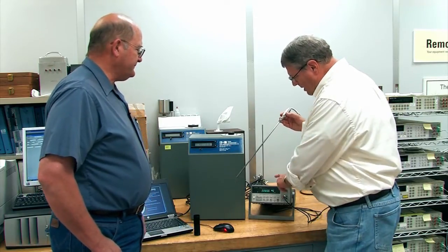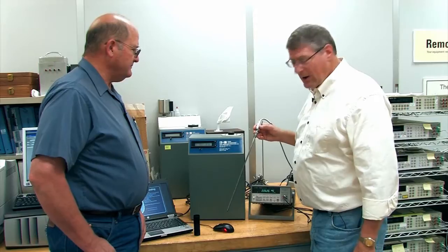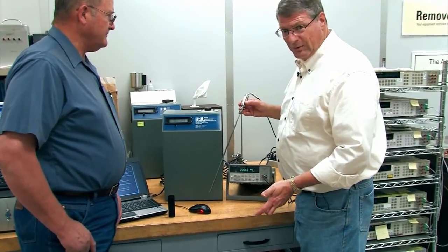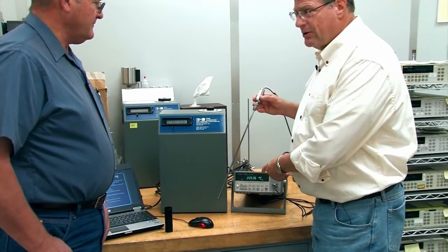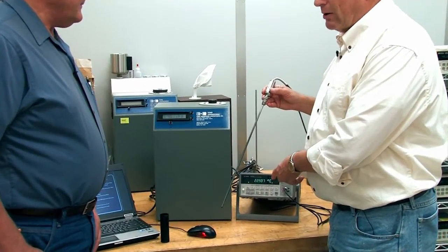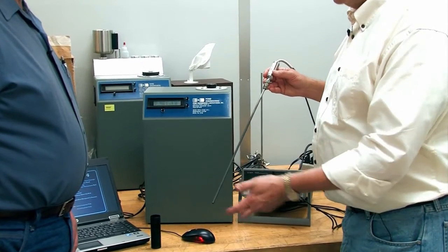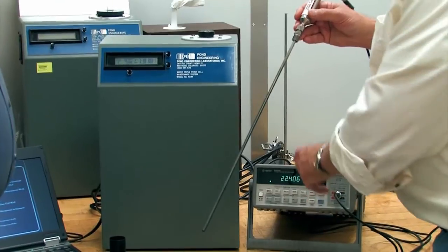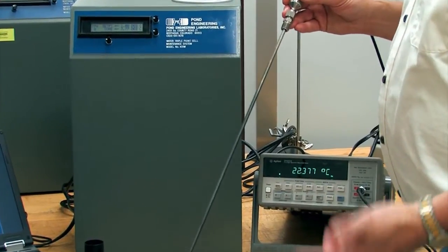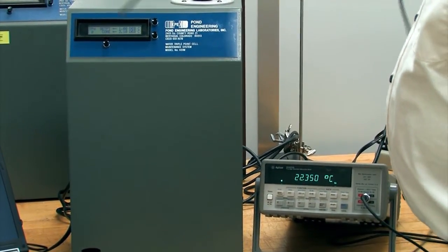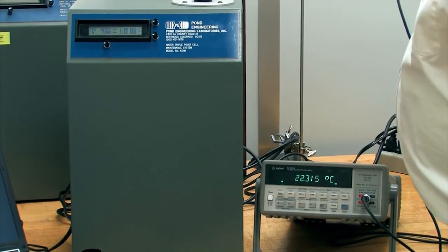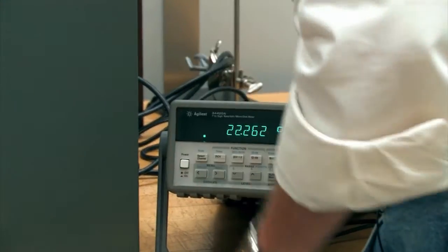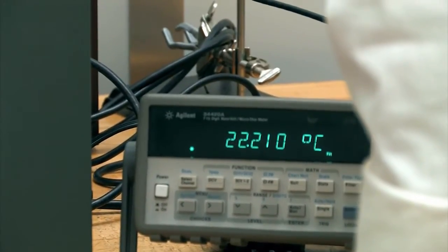Okay. So I'm actually using a 34420A. This is Agilent's nanovolt micro-ohm meter, and we're doing resistance measurements. We're on the 100 ohm range, and we put it in the low power mode because of what you talked about. We don't want to heat up the element. We're also doing 4-wire ohms, obviously, and we have some other things in here like offset compensation, and we're doing some other magic trying to take the best measurement possible. So can I do the honors? Yeah, absolutely. All right, I'll try not to break anything. I slide this down into here. Eventually it'll stop. Oh, okay, I found the bottom.